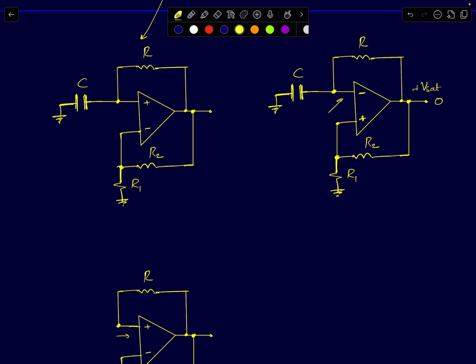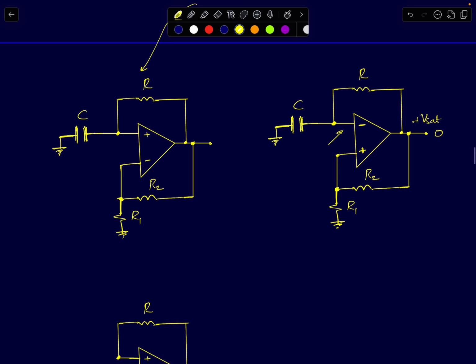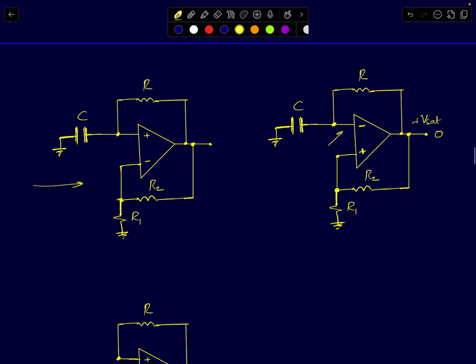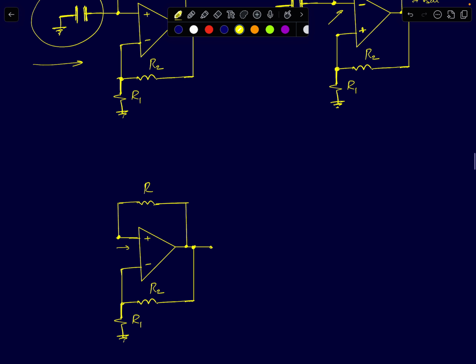So when you're given a circuit like this, the first thing you need to do is analyze this circuit at steady state, meaning you can treat this circuit like a DC circuit. At DC, capacitors behave like an open circuit, so the circuit reduces to something like this. Now you have a familiar circuit that you can easily analyze.